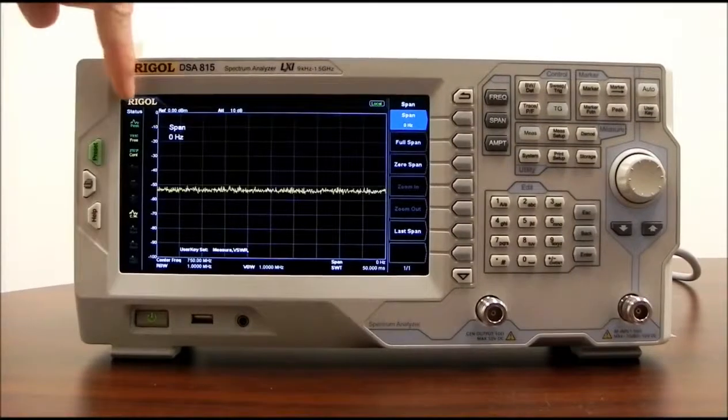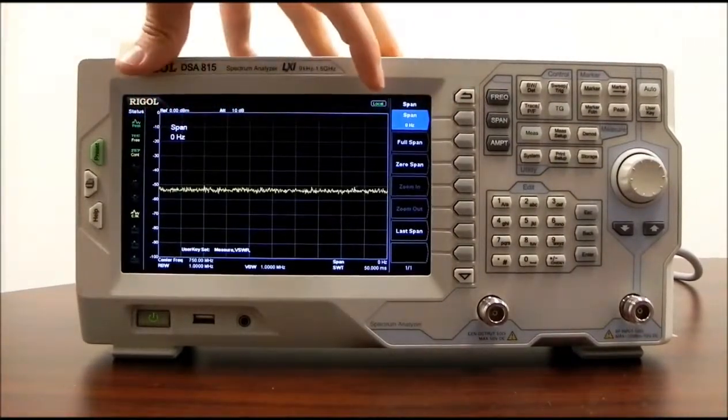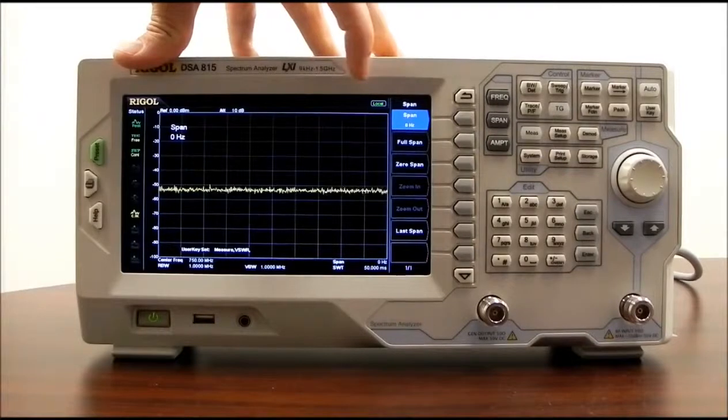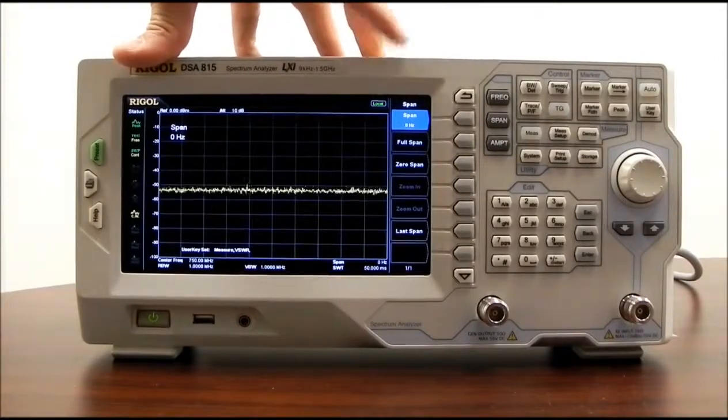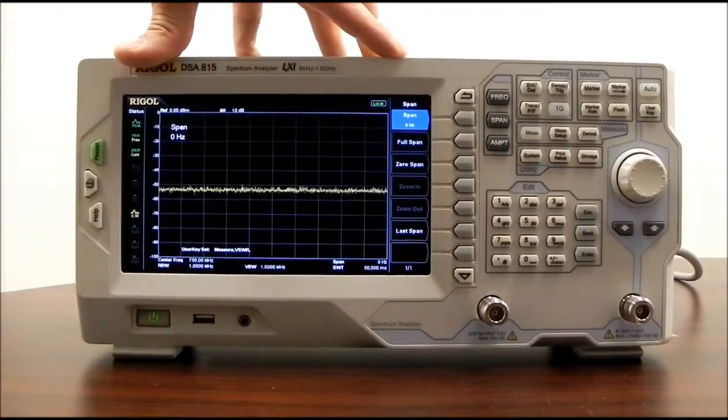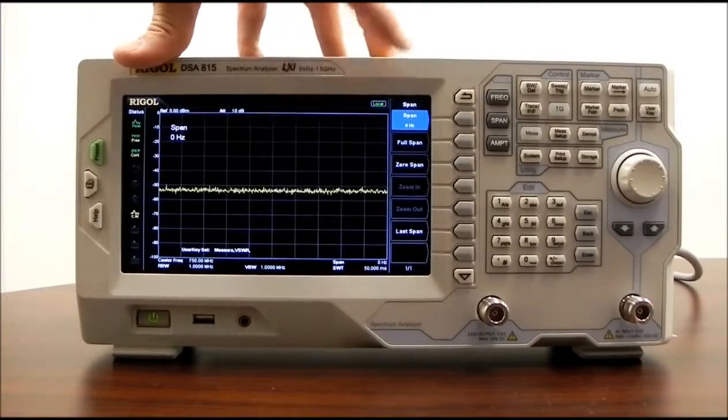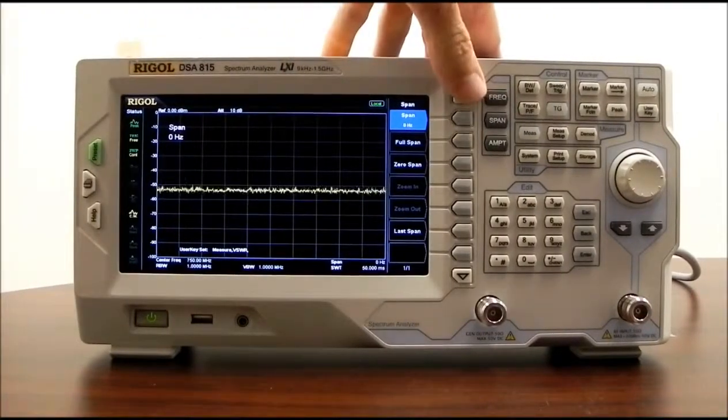And now this is with amplitude with respect to time. So you can actually look at time varying signals or the actual modulation of the signal at that particular frequency level. You can think about it as a limited bandwidth, extremely limited bandwidth oscilloscope. Now you can use that if you have a particular code or something like that that's being sent at a particular frequency level or value. You can watch the actual bits, let's say, of that signal coming through, which can be helpful.